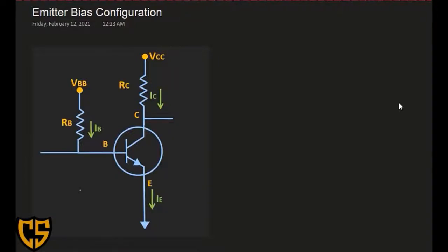Okay, on the previous video, we discussed the fixed bias configuration. So take note of this one. This is our fixed bias configuration. If we set the resistor in the base, which is RB, to a fixed value, the tendency is that your current IB will also be constant. However, despite having a constant current at your input, which would influence the value of your current IC, the operating point, or our Q point, will still be unstable.